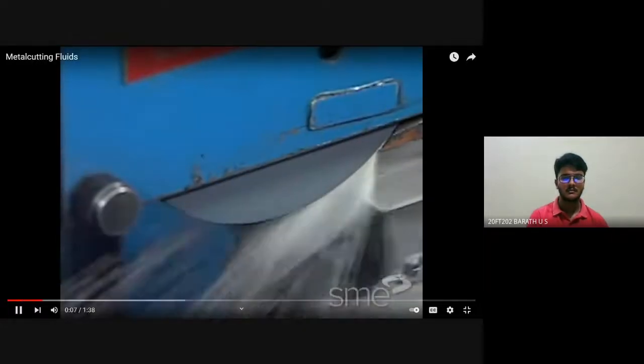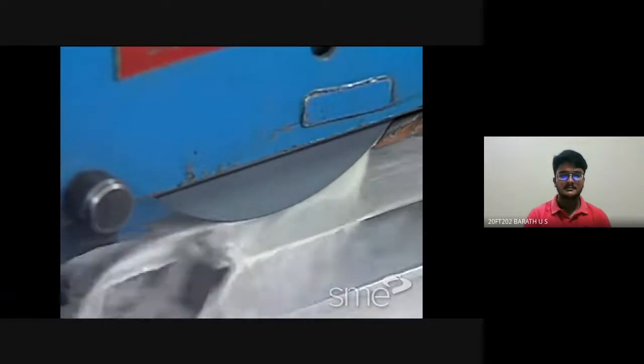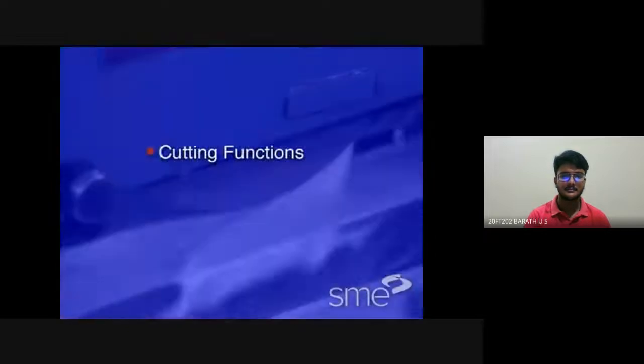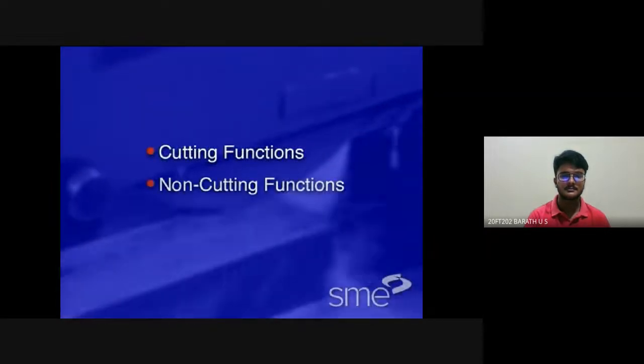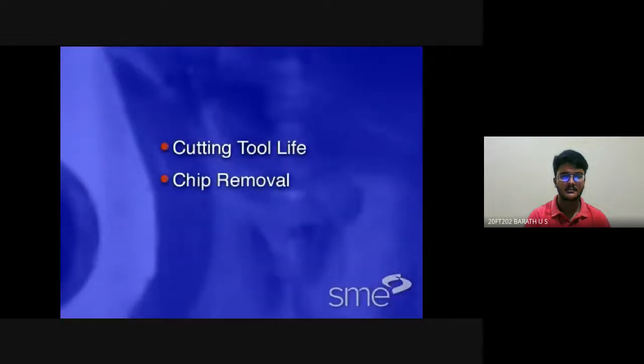There are many factors to consider when selecting which cutting fluid, if any, is appropriate for use in a given machining operation. Generally, these factors can be classified as either cutting functions or non-cutting functions. Cutting functions actually affect chip formation and influence cutting tool life, chip removal, and surface integrity.